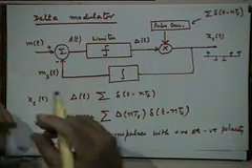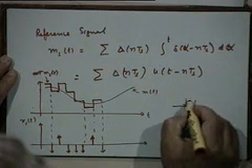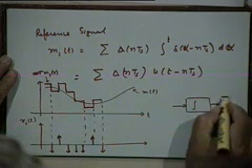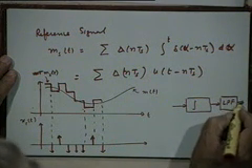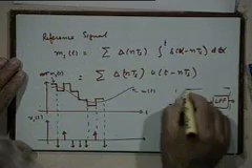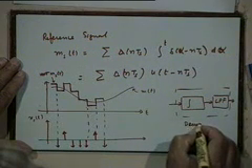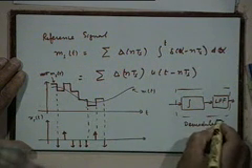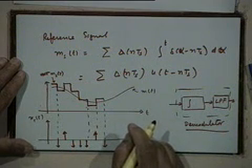Only thing is, it is a kind of crude approximation, and if you want to remove those steps, you should pass it through a low pass filter to remove the high frequency components which are present in the edges of the step functions. Is that clear? So the demodulator will essentially be an integrator followed by a low pass filter. So that is your demodulator. Really very simple.